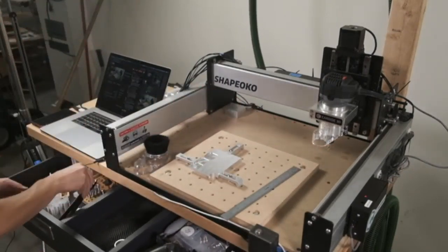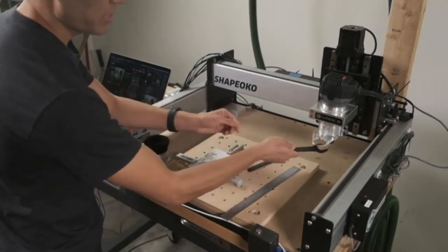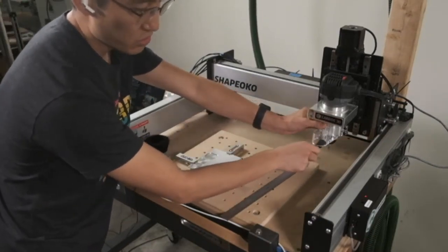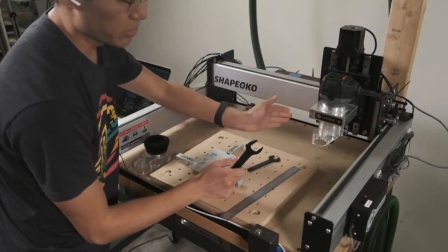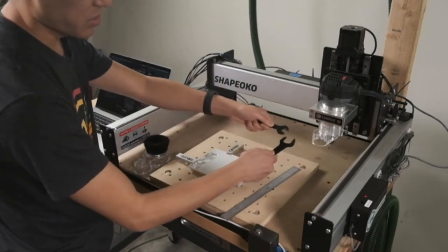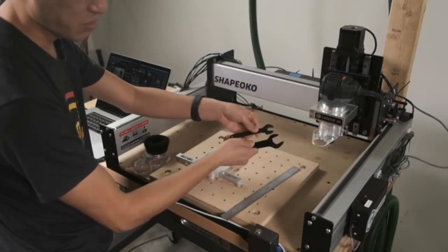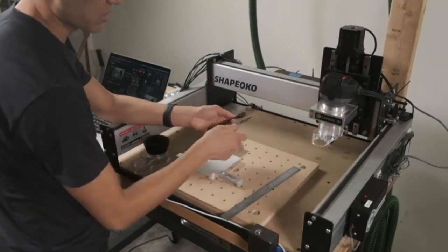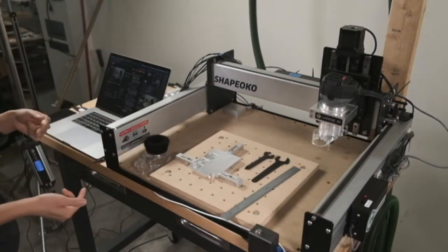if you do it with only one wrench and you just use the spindle lock button and you are torquing on the spindle, you're also applying a lateral force. So you can bump the stepper motor and shift it a step if you really force it. By using two opposing wrenches, you cancel out the lateral forces and you get pure torque. So using two wrenches prevents you from accidentally forcing the stepper motor to miss a step. That's usually the only case where I would see an issue with a misalignment.